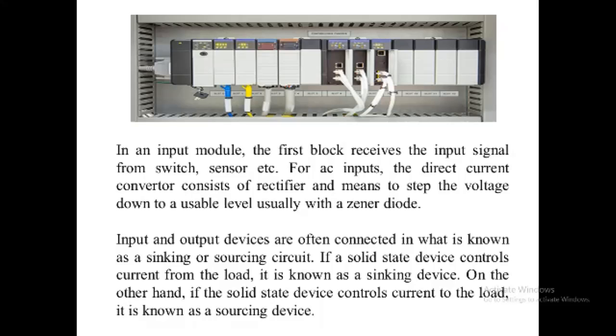Here auxiliary means not an electrical appliance, but electrical controlling machinery, like push buttons, relays or contactors. These are connected on the negative side, and in the latter case, the load is connected to the positive side, meaning the devices to be controlled are on the right side of the power supply.